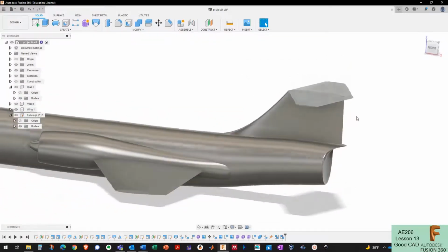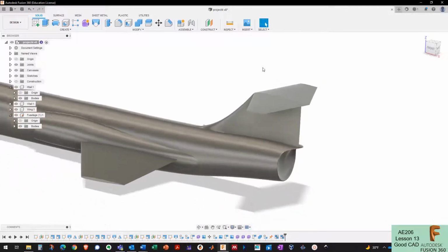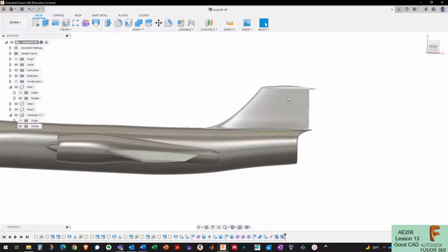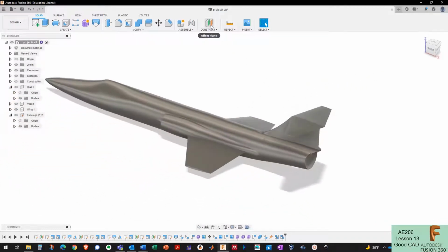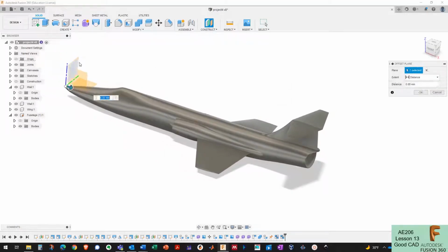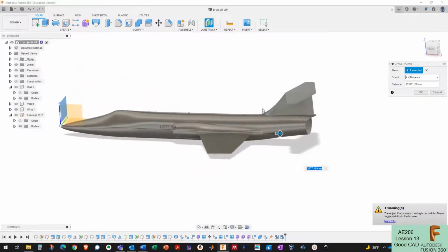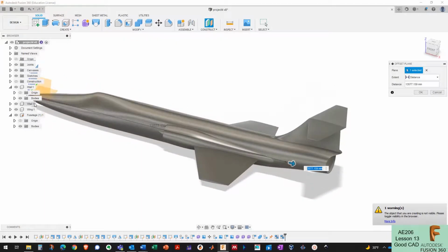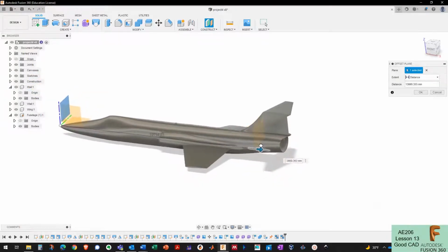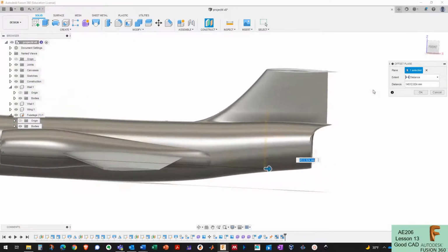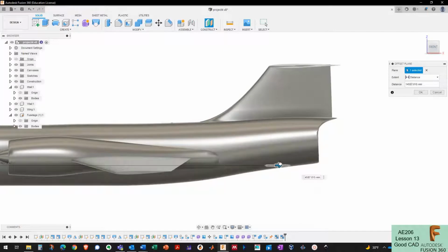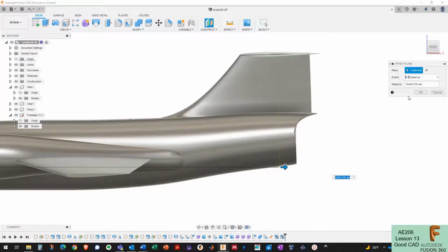So what I'm going to do is put a rudder on my aircraft here. I need to split my vertical tail right about here, and the way I'm going to do that is by using a construction plane. I can drag a construction plane back here, and it's giving me a warning because I can't see the construction plane I'm making, since I turned them off, so I'm going to turn them back on. Now I can see my construction plane, and I'm just going to do a rough position here. I'm going to call that my rudder back there, so a fairly good sized rudder.